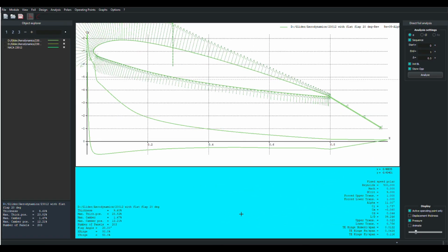Okay, I'm experiencing the same results that I received last night when I was running through this stuff, which is that when you deflect the flat plate elevon on this airfoil, the Xfoil program has a hard time calculating through some of those angle of attack ranges. It's where we saw the little burble in the lift curve slope.